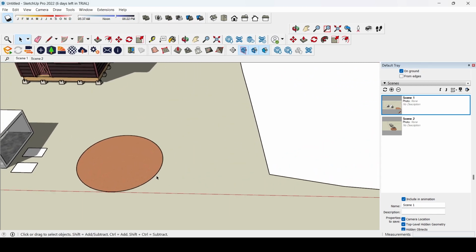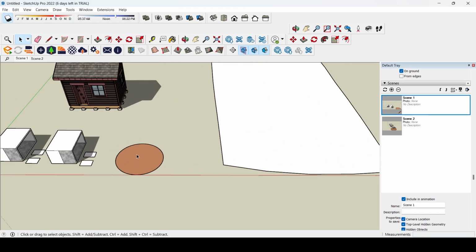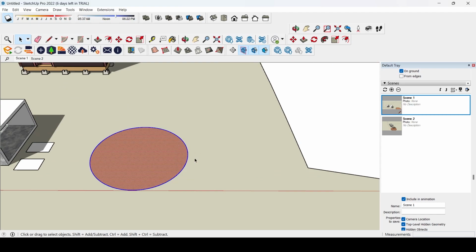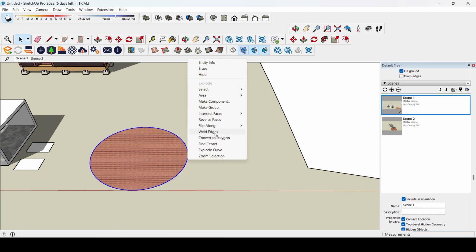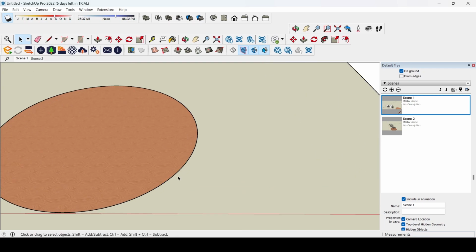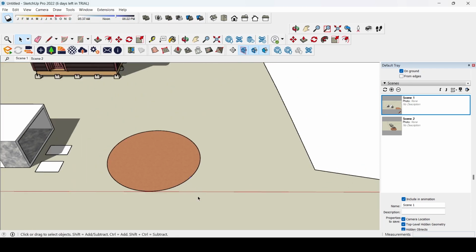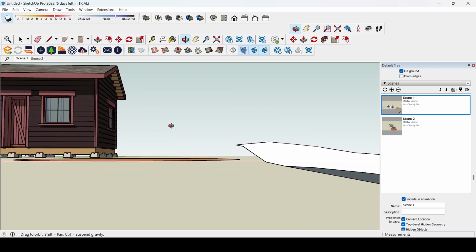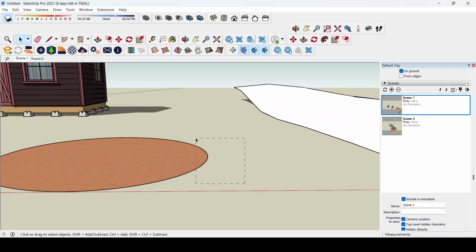If you are going to mark something in SketchUp, let's say this one here, I'm just gonna explode these segments here, so they are individual. Let me just click that one and Explode Curve. So now you can see it's many curves like this. What you might notice is that if I do like this, it's gonna mark the face. And that's because I'm dragging from bottom right to top left.